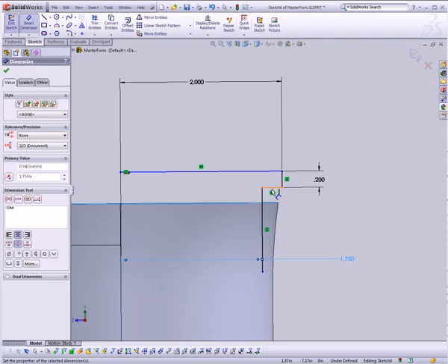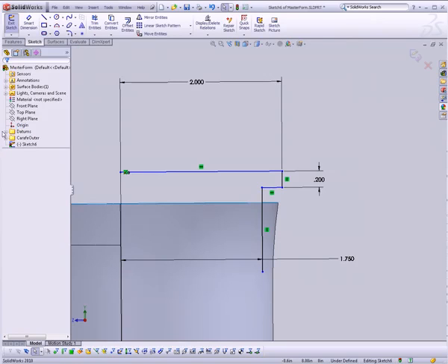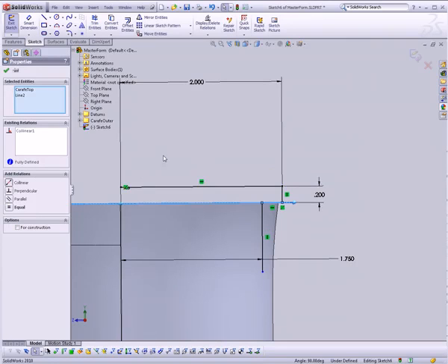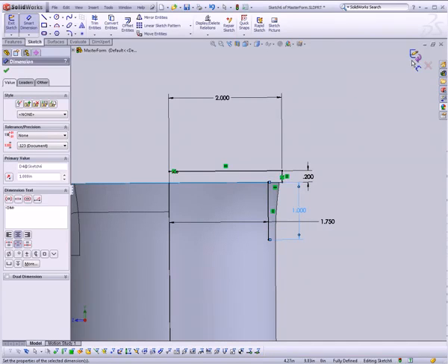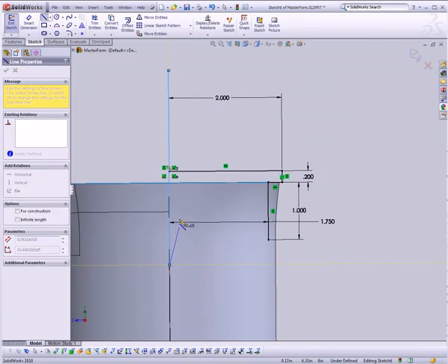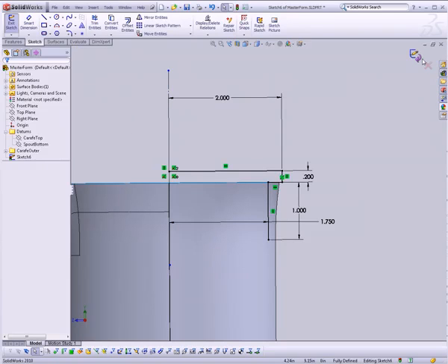And lastly, we want for this edge here to rest right on our carafe top plane. Control click those two and say collinear. Oh, one other thing. I need for this line to be 1 inch long. And finally, last thing, promise, last thing this time. Need to draw a center line. There we go.